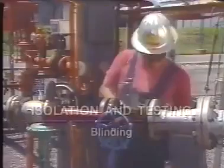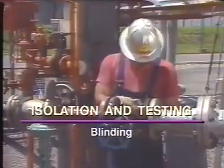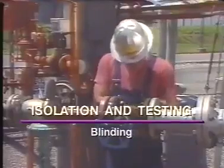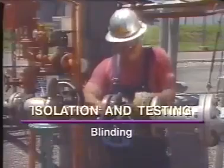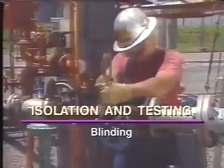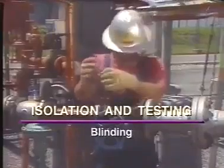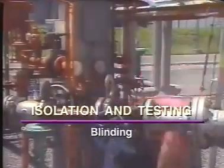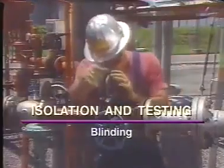When a column is vented to the atmosphere, there is a possibility that hydrocarbon vapors from other parts of the unit will enter the tower and form an explosive mixture. To prevent this from happening, metal plates or blinds are placed in all tower inlet and outlet lines. Blinding a tower effectively isolates it from hydrocarbons that are present in other parts of the system.